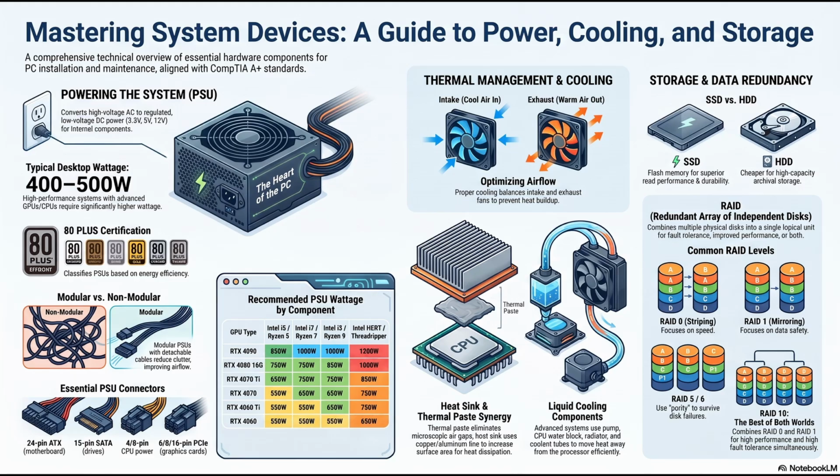As motherboards started absorbing all these features natively on board, 5.1 surround sound, gigabit networking, a dozen USB ports, the power draw on the board itself skyrocketed. Oh, that makes sense. Furthermore, the PCIe slots, which we will get to, needed to deliver up to 75 watts directly through the motherboard traces to expansion cards. The original 20 pins simply couldn't carry that much electrical current safely without the wires overheating.